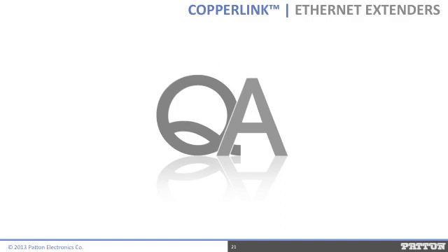Thanks so much, Ed. The next question looks like it's for Nathan. Nathan, this attendee would like to know, what is the difference between deterministic and non-deterministic networks? Thank you, Katie. It's a good question that many people don't understand the answer to. Token Ring is a deterministic network because it guarantees the delivery of the data packet. Standard Ethernet, being non-deterministic by design, does not guarantee delivery. We all know that if a standard Ethernet link reaches 80% traffic, the chance for collisions rises exponentially. The industrial protocols have been modified in various ways to create deterministic network behavior in an inherently non-deterministic network. The reason is to meet the requirements of real-time industrial applications.